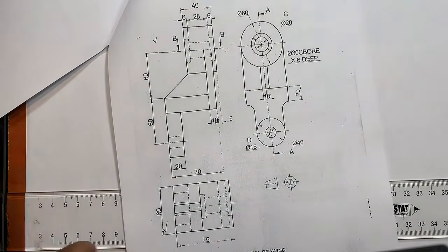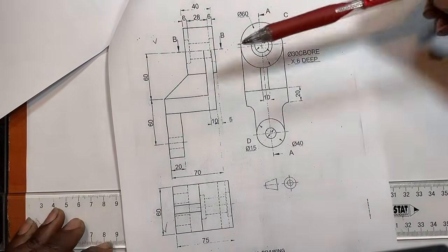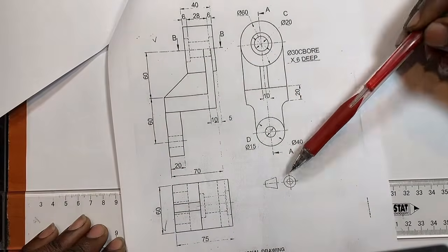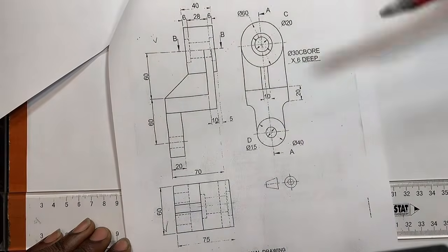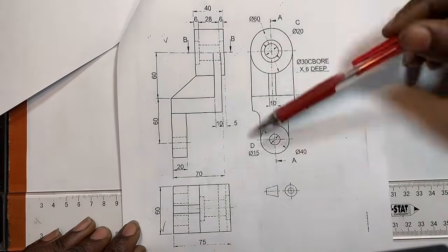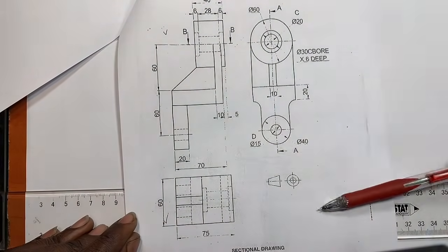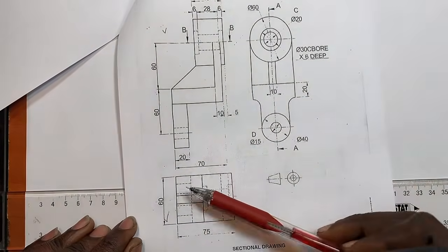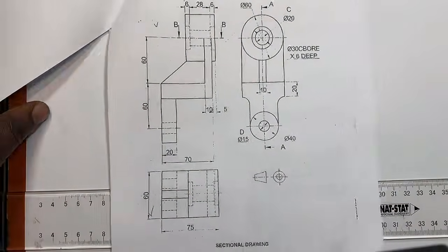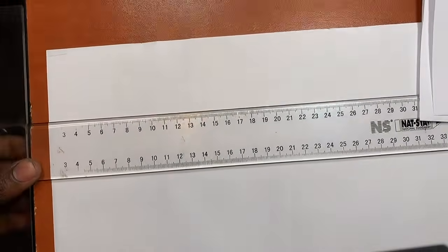So another thing that we have to look at here is what? Is that they said to draw this according to first. So which means the left view, my brother, you are going to draw it the way you see it. The left view, you are going to draw it as it is, so that you project lines. Once they touch this line of 45 degrees, then you take it towards your top view, so that you're going to get your top view. Okay. So now I can start. So it's actually necessary for me to start a little bit up on my drawing sheet.